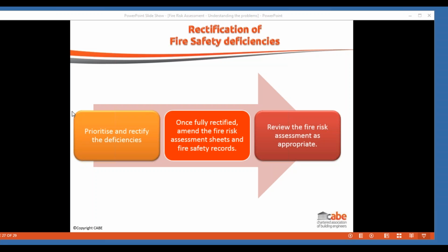If something varies from what we see in written guidance, it's always sensible in the first instance to take a step back and say, well, what's the principle of the guidance? Why is it there? What's it trying to achieve? And normally when it's things like travel distances or distances we have to move people, what we're actually looking at is the time that it takes to get out. And the distance that goes into a lot of standards is actually a reflection of the time it takes to get people out of the premises. Now in a care home, it's going to take longer anyway, because we're trying to assist people. People are not as mobile, perhaps they're more elderly or whatever, so they may take longer to escape.